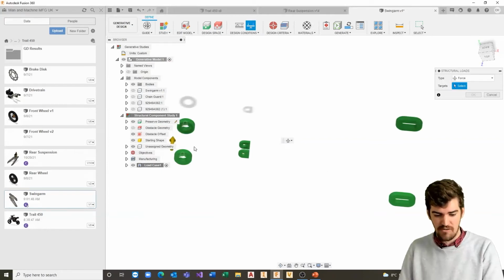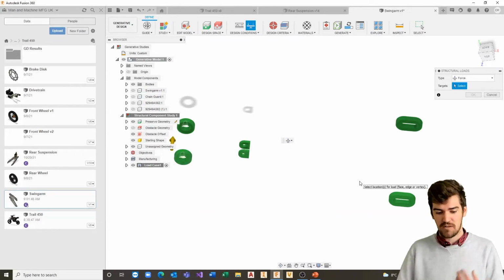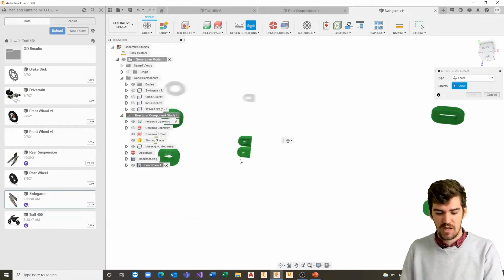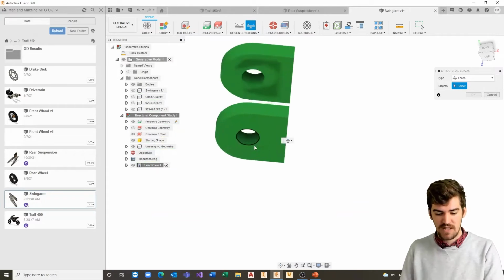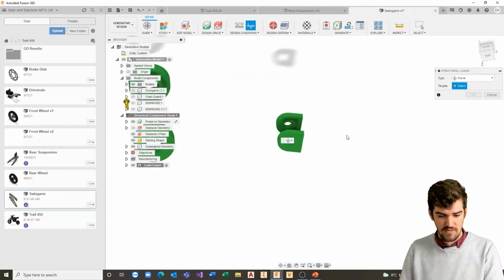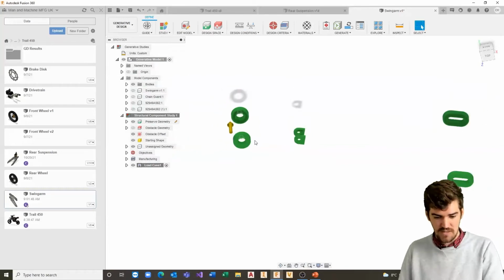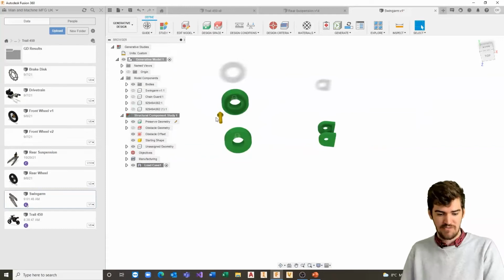With this other area here sat still, the rest of these will essentially be moving towards and away from that origin point. And we want to be able to create a structure that will be able to withstand any of the movement that will come across from there. So the first thing I want to do is, there is a gravitational load that's already assigned. I just want to make sure that that's pointing in the right direction. You can see here it's not pointing in the right direction.